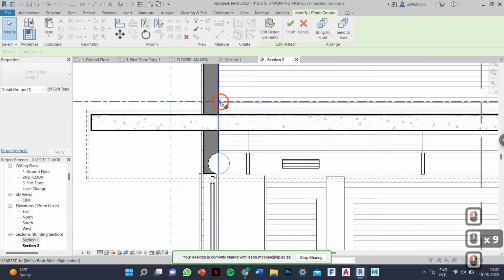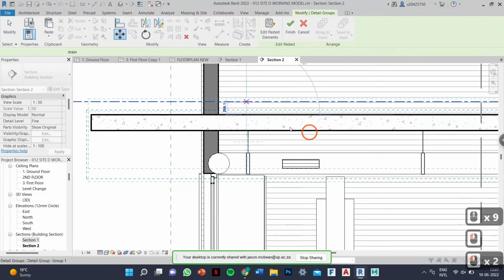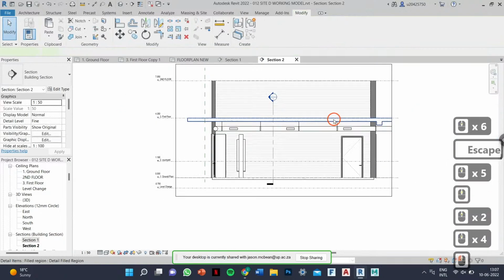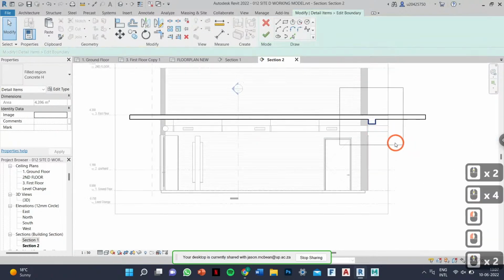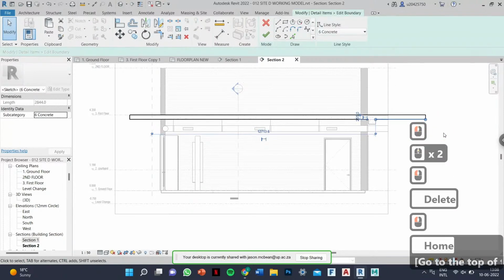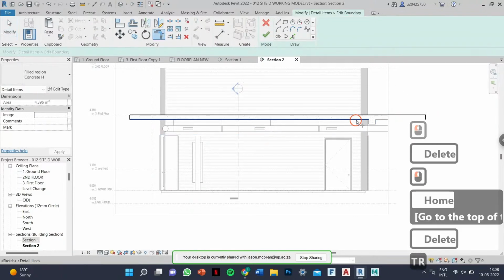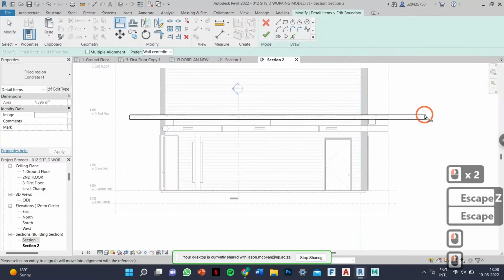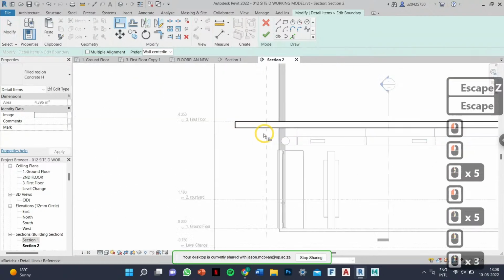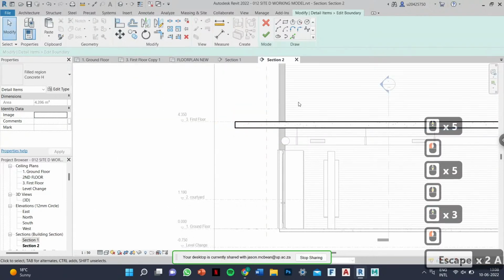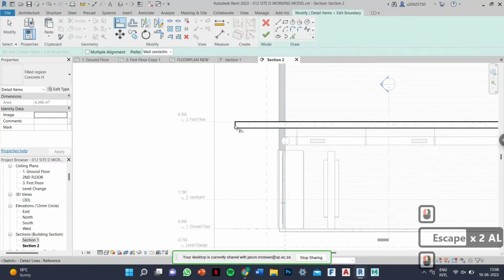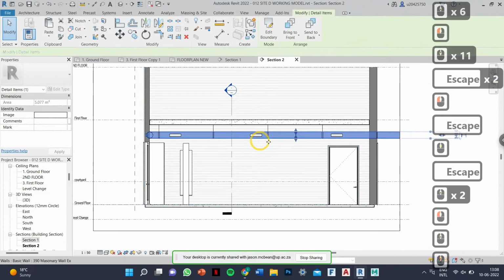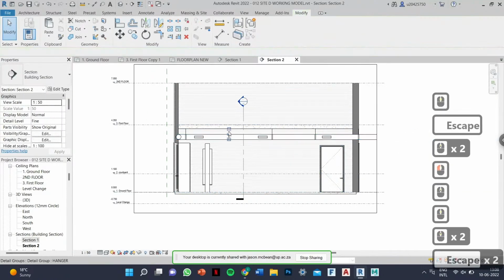Yeah, so what you do is you move it in, you have to have a plane set up. But there I've connected this straight to the same level. But what's neat is, watch this. Edit boundary. Let's get rid of that. Delete that, delete that, delete that. Trim that with that. Watch this, align. So using the align command, align it. Voila. Align that with, come on, that. There's my concrete slab. This guy, now I can move this, edit this, and now the arrays are still going to work.